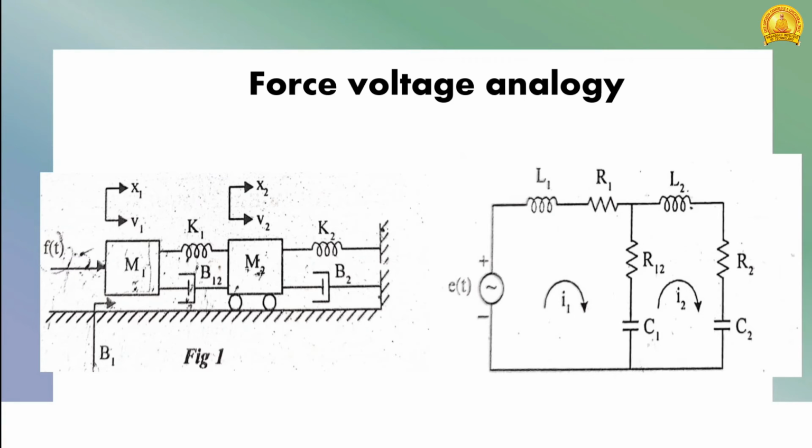These two should have the same current, so they will be connected in series in the electrical circuit. Checking the figure of the mechanical system, we know that these are not common to the node 2, so they will not be in the common branch. So represent these L1 and R1 in series in any other branch rather than the common branch.